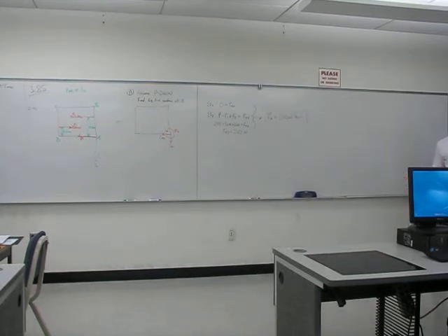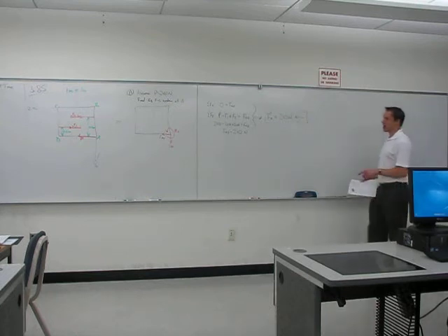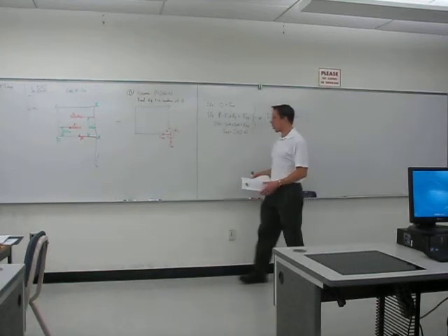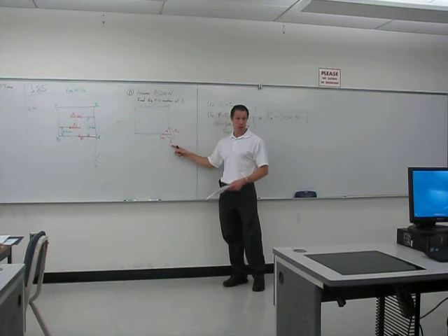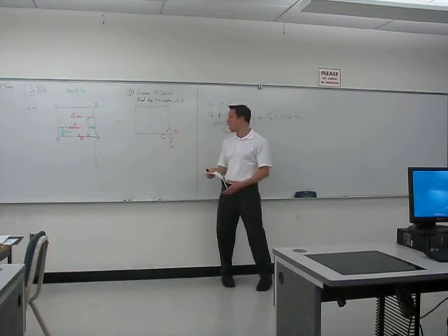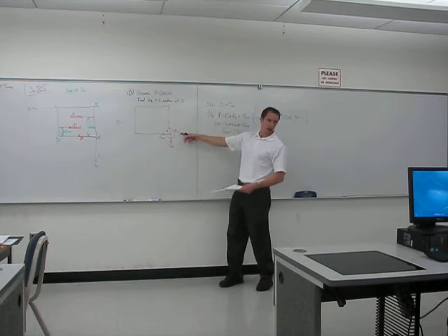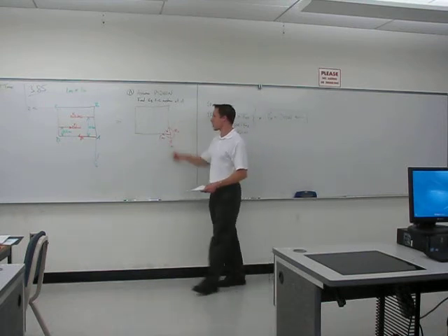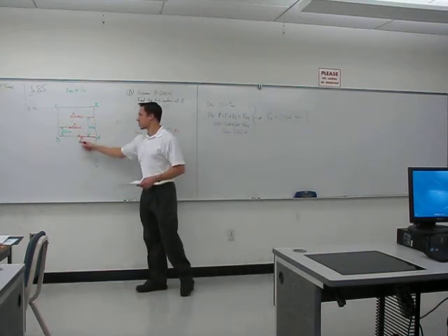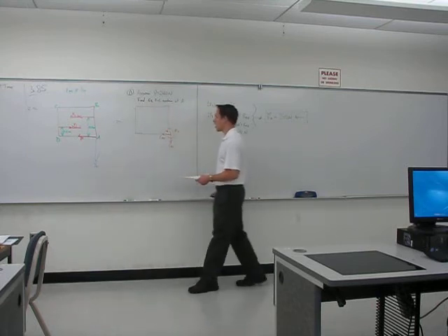That's only half the answer, because you see it says find an equivalent force coupled system. Well, we found the force, whose components we see here, FAX, FAZ. We know what the actual force is now. We have to find the other half of the solution, which is the moment vector. That's going to make sure that this crate rotates in the same way that this system of forces would want to make it rotate.